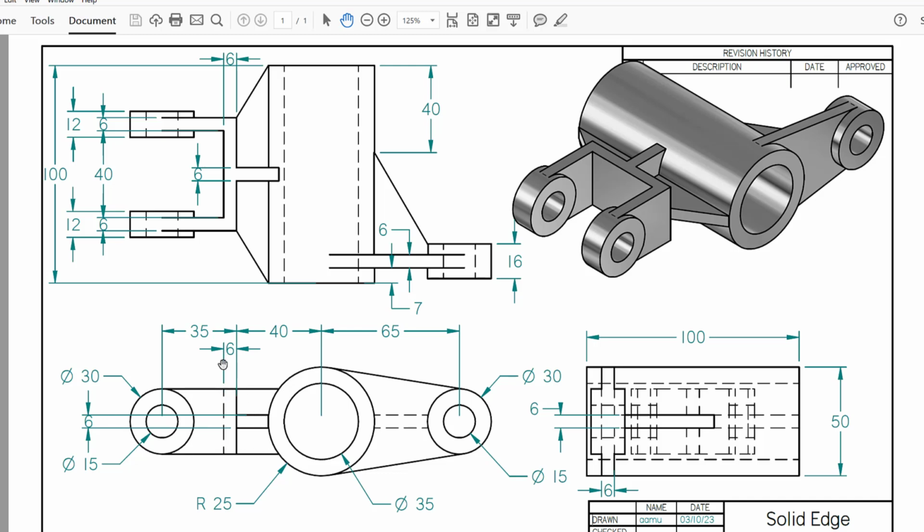So 6 by 30, and this distance here is, if you look carefully, 40, sorry. And it is symmetric here, so I'm going to extend it another 3 millimeters to the top and 3 millimeters to the bottom. This way I will have 46. This is what I'm going to extend, actually 46. Then I'm going to lock myself to the plane and make a symmetric plane here and a symmetric extrusion from here, which the first one will be 6, meaning 3 and 3, so you will get the exact dimension, and 12 and 12.